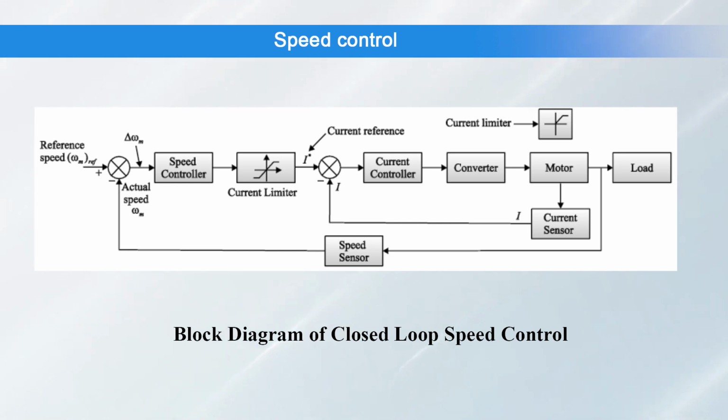The speed error is amplified by the speed controller, which is more accurately described as a speed error amplifier, and the output serves as a reference or input signal to the inner control system. The inner feedback loop is a current control loop. So, when the current reference increases, so does the motor armature current, which provides extra torque and initiates acceleration.